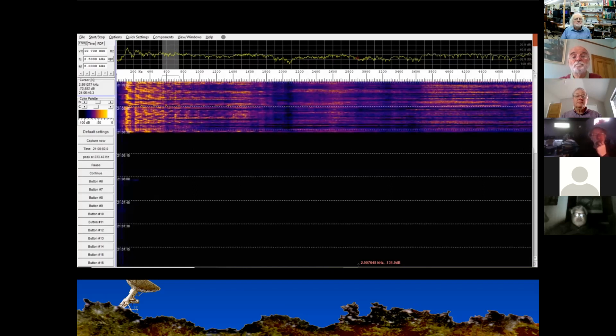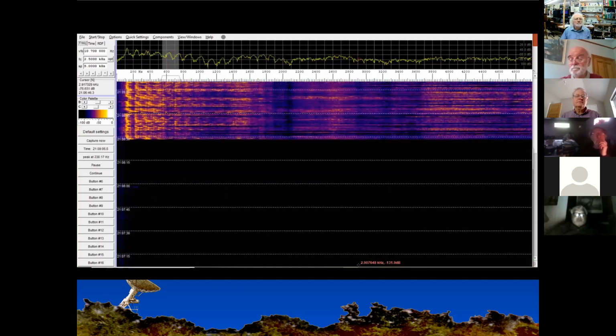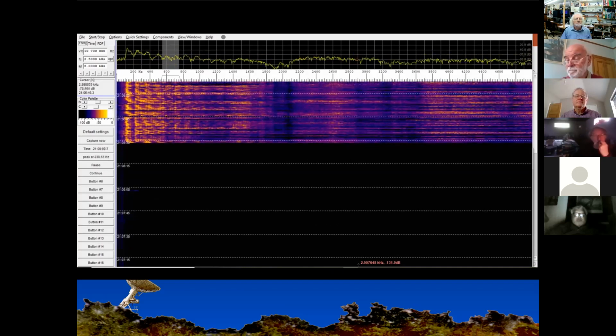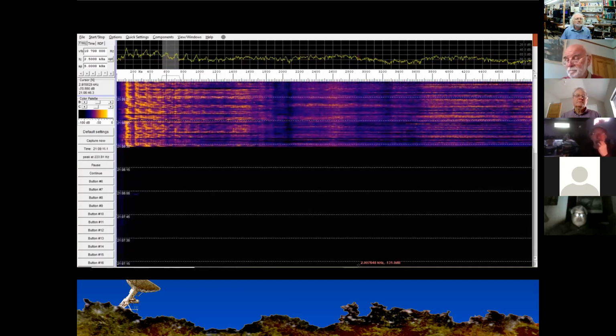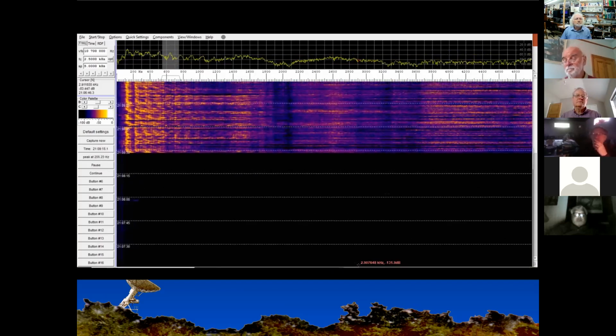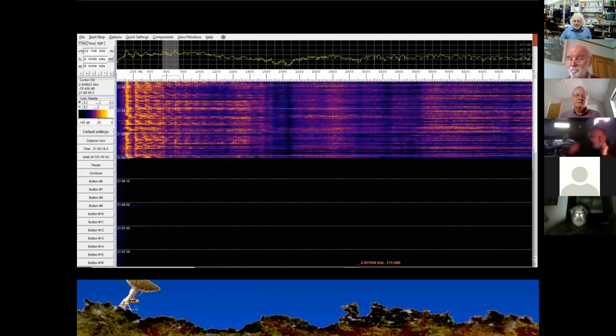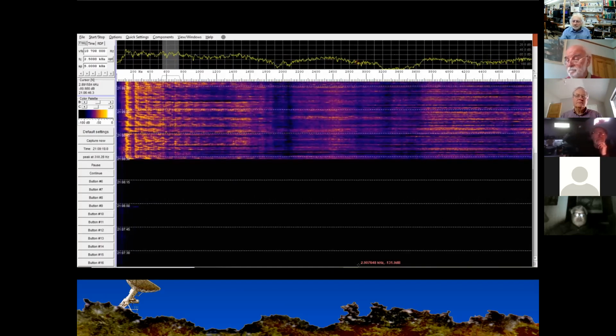We plug our loop antenna into a microphone socket. Now, I recommend that you use an external USB sound card on the end of a USB extension lead, because then you can locate your loop antenna away from the laptop or other possible sources of interference.